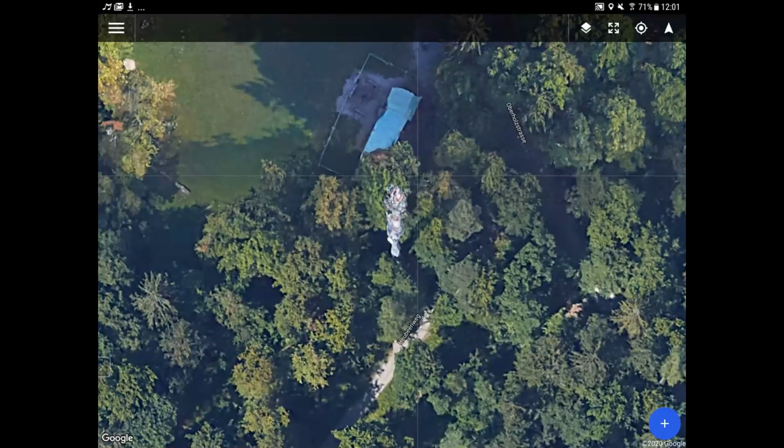And this is very important when you do something like a cell tower inspection where you fly several meters away from a tower. It's very important to perform the calibration. This calibration accounts for modeling errors that we incur when we create the model of the tower, as well as the inherent GPS inaccuracy and shift that the drone's GPS might have. So both of these things are accounted for using a calibration flight. But I will not go into great detail into calibration in this video, in this webinar.